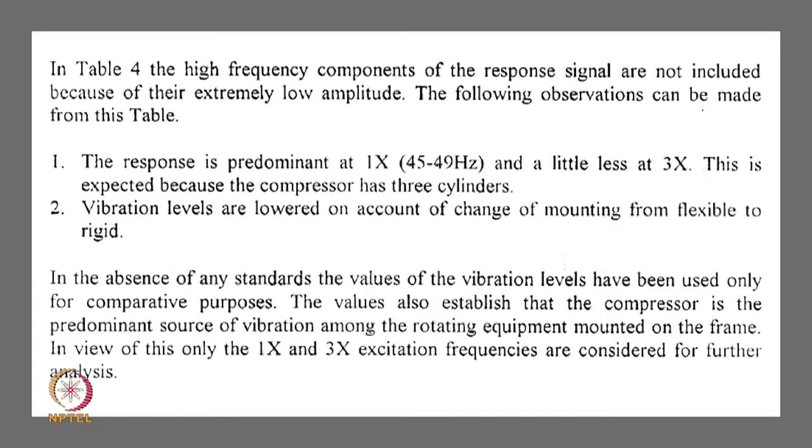Now in table 4, the high frequency components of the response signal are not included because they were very low and they were not resulting in any significant impact on failures, which was the primary objective of the study. At 49 hertz, 45 to 49 hertz, and slightly less at the 3x, which is in the 133 hertz range.